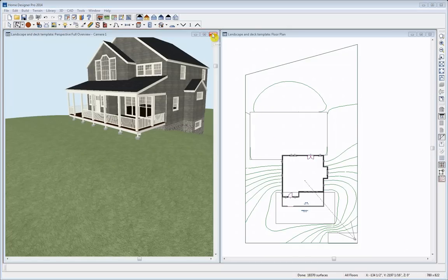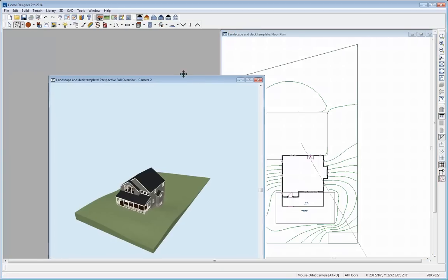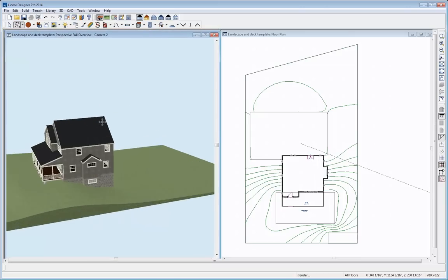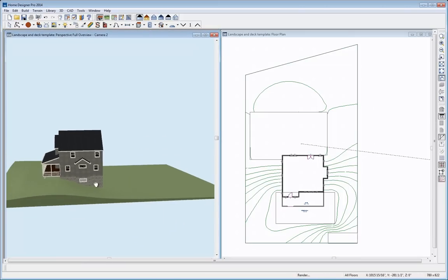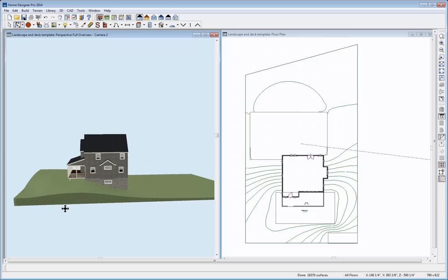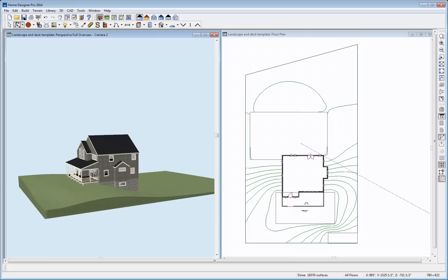And it looks like my perspective for this camera got a little bit off, so I'm going to exit out of here and create another 3D overview so we can start from scratch with that. And now I'll zoom in. So as I was explaining before when we had the terrain specification open, this is the skirt option. So you can see the depth of the terrain at various points throughout, as opposed to simply following the terrain where you would simply see a 12-inch line that curves around.